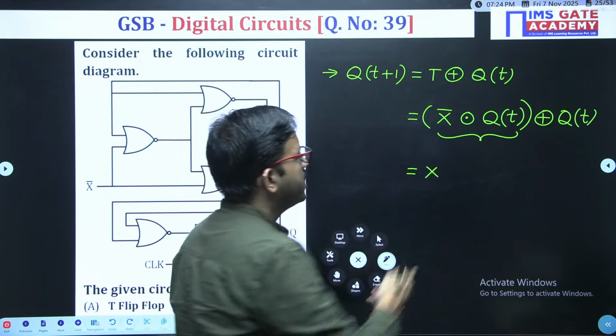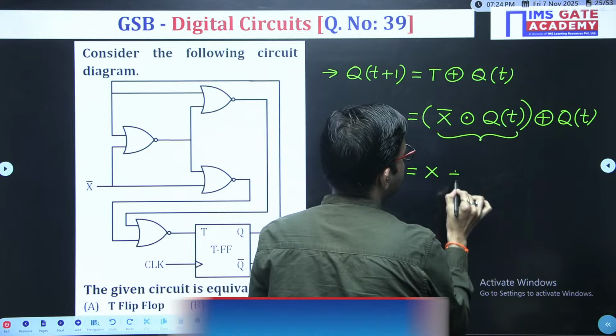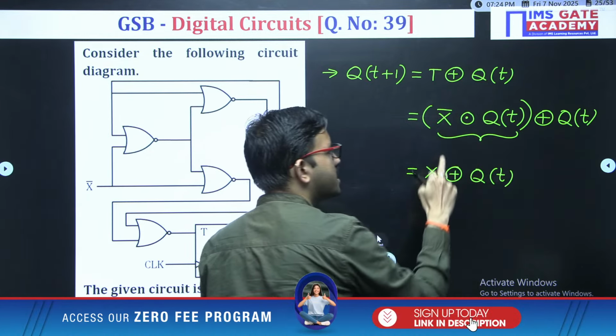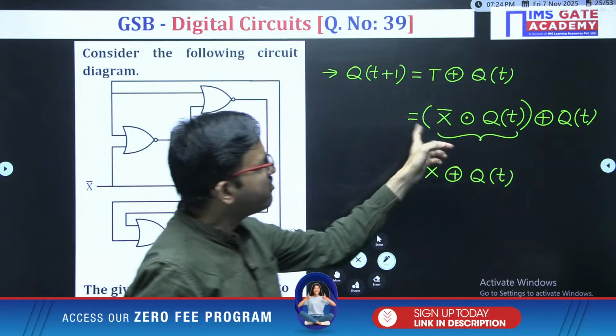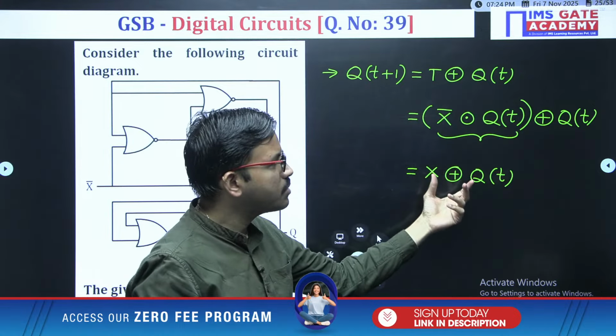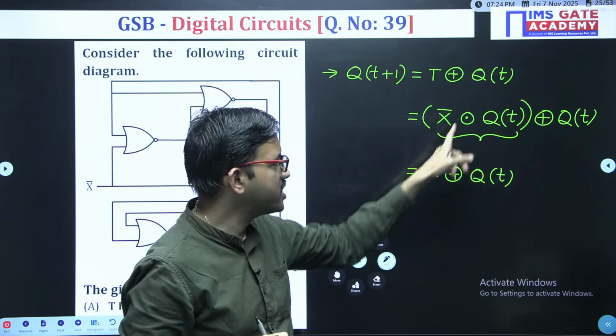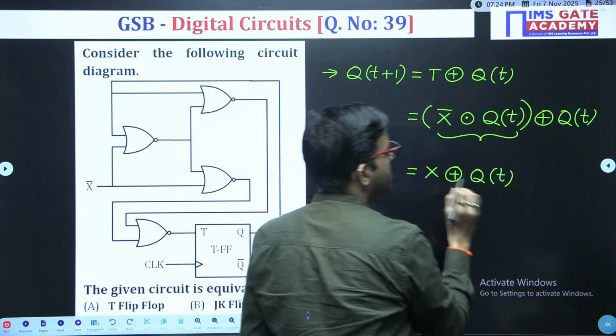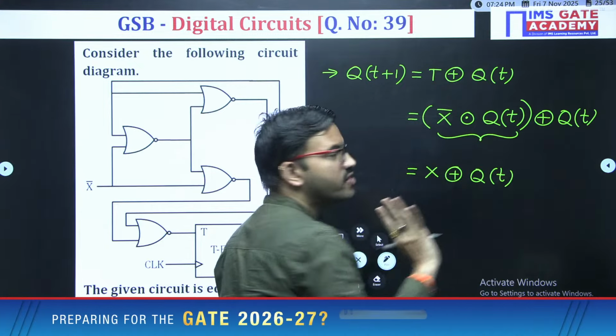Since XNOR is there, XOR will come, and if XOR is there, XNOR will come. But if both variables are complemented, then it is exactly the same operation as with the normal variables. You can give it a try in your free time. It is applicable for 2 inputs.